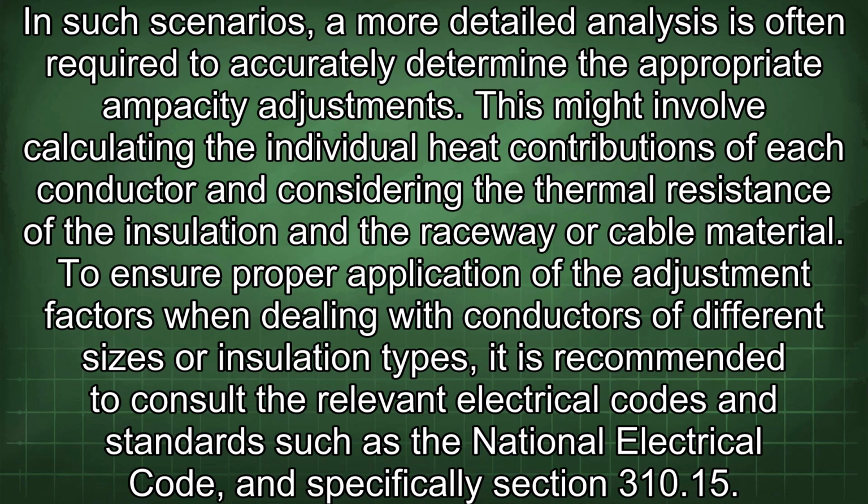In such scenarios, a more detailed analysis is often required to accurately determine the appropriate ampacity adjustments. This might involve calculating the individual heat contributions of each conductor and considering the thermal resistance of the insulation and the raceway or cable material.